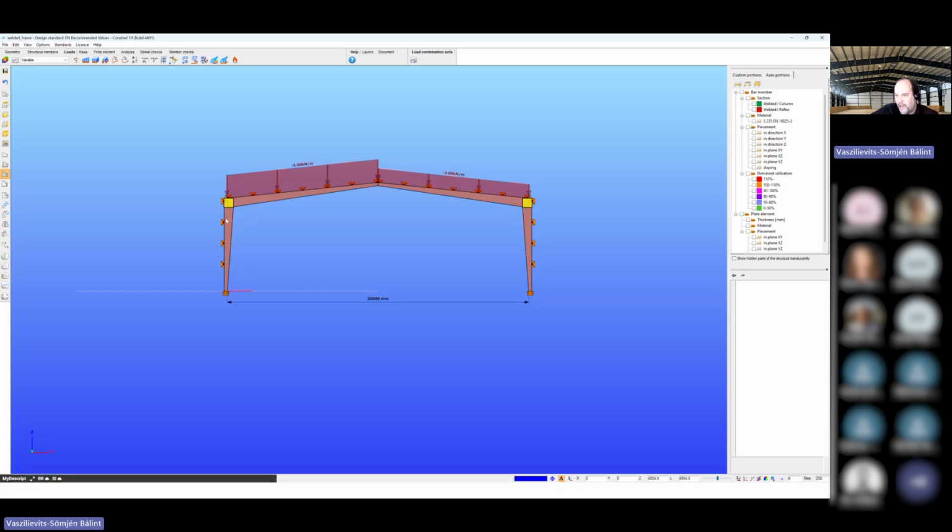So here this section stands with its major axis and is 600 millimeter deep, while the flange is only 100 millimeter wide. So obviously, just dimension-wise, it is 6 times bigger. And of course the whole topology of the section is that it creates big inertia in this direction and very small in the other direction. So the two inertias are very different. And even if we have intermediate supports along the length, almost always the out of plane will control the design. But it doesn't mean that we are allowed not to do the in-plane. In-plane must also be done.